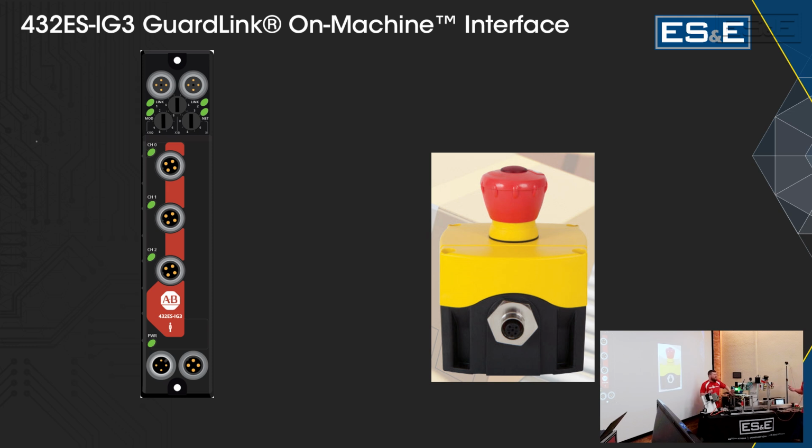Traditionally, safety circuits are run in series, and to get diagnostic information you would run auxiliary contacts to input cards on the PLC. What GuardLink does is eliminate the need for those input cards and give you that diagnostic information without the additional I/O requirements.